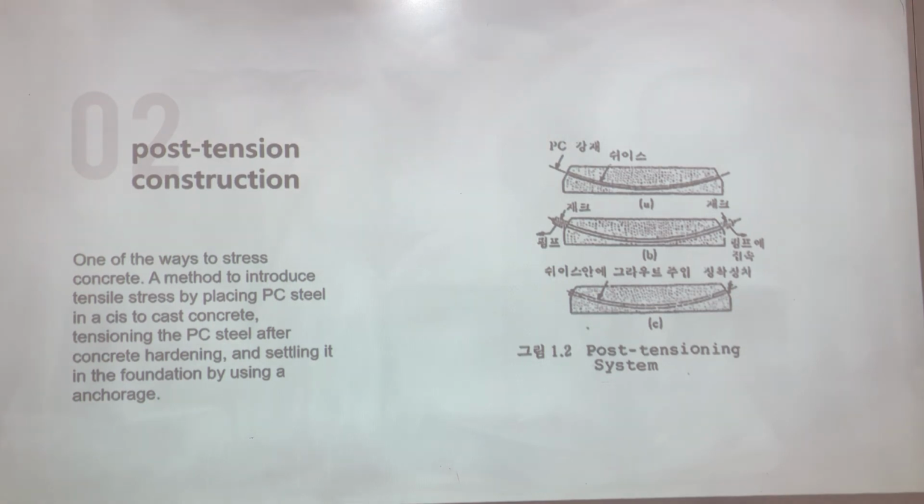The advantages of this technique are the durability of concrete and its resilience, and it's easy to assemble, design large spaces, and increase the number of floors. The disadvantages of this technique are the possibility of vibration and the possibility of damage to the tendon. And the construction is complex and requires a high level of technology for design and construction.